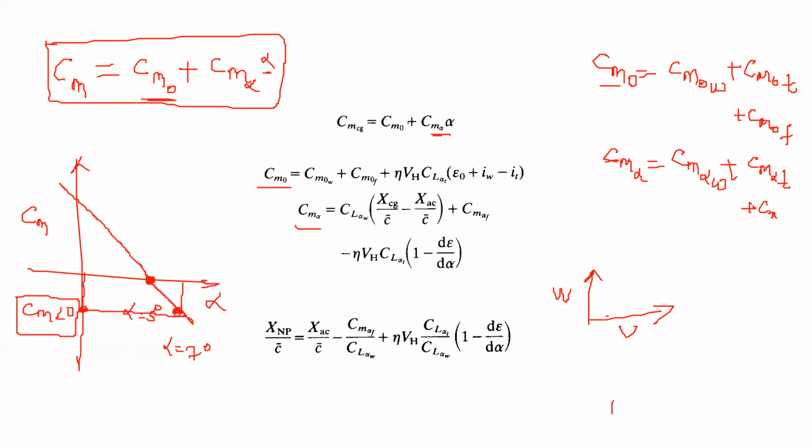Pitch down, right? So when you pitch down, it goes from 7 degrees to 5 degrees, or maybe it'll go to 4 degrees. Let's say it goes to 4 degrees because it doesn't stop immediately. So it will go past this angle and go to an angle of attack of 4 degrees. But at 4 degrees, what happens? It meets a Cm that is positive.